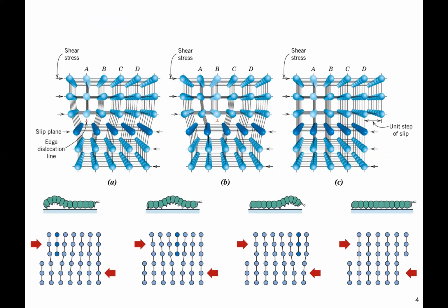So when we were talking about edge dislocations, we were talking about how they move. As you remember, here is the half plane that has now shown up in your material. It's an extra half plane. And the way it propagates upon a shear force, you can see this way. You can see that it doesn't just instantaneously shift, right? It's not like you move the whole plane and now it's over here. It shifts pretty gradually.